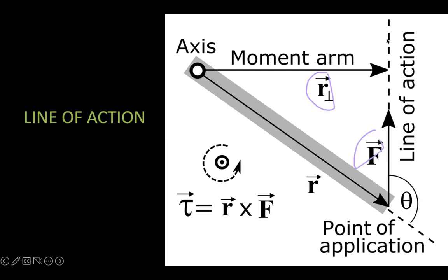As you can see, it connects on the line of action, and basically F times R sine theta means that we only want the y component of the F force, because only that is producing a moment. Only that part of the force is helping to turn this structure. This entire structure represented by this.